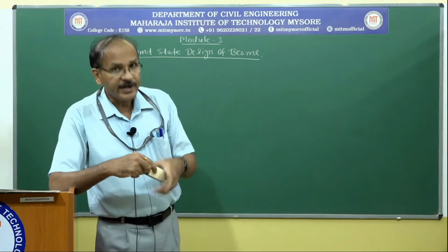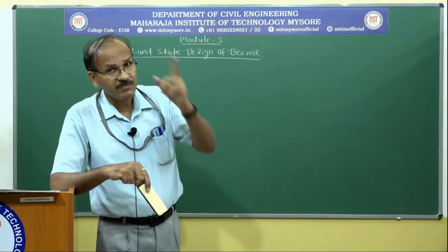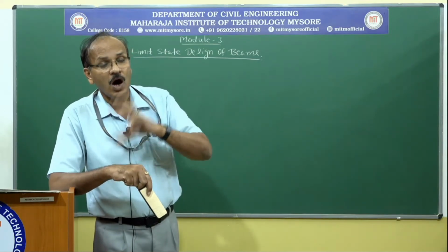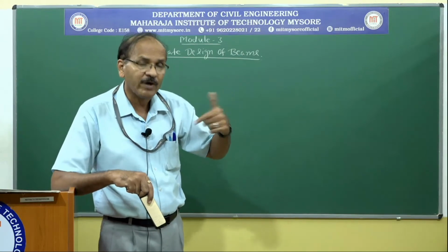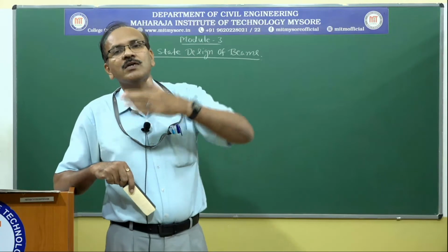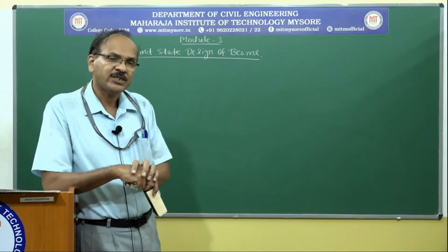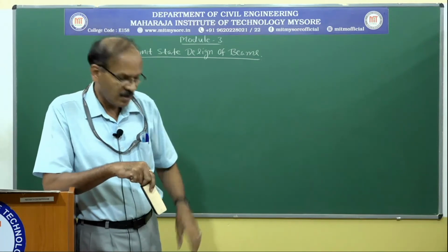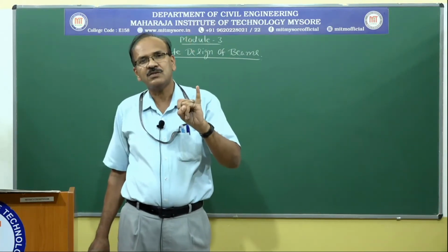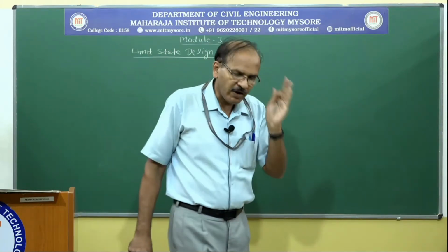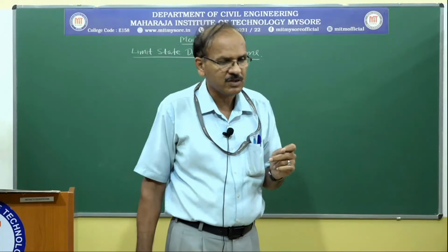In addition to that, we are going to calculate the maximum shear force developed as a result of the external load. How much bent up bars need to be provided, if at all we are providing them, and what stirrups we need to provide: what are the diameters, how many legs of stirrups, and what spacing we need to give, whether those spacings satisfy all IS recommendations, etc. We also check for deflection. Here we fix the dimensions, we calculate the area of steel, and we find out the stirrups to take care of shear. We are going to find out the spacings of those stirrups, etc.